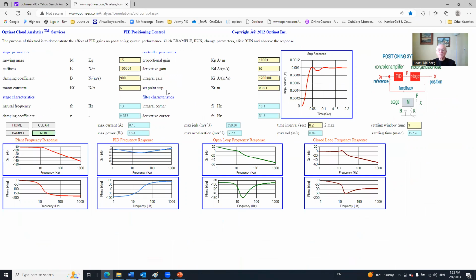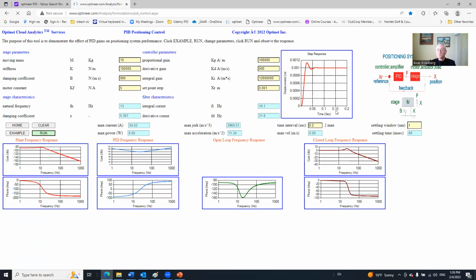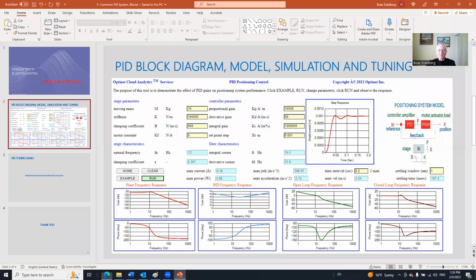We see over here all the variables. We can try to tune it, and this will be part of the exercise that we'll do in homework. But if, for example, we change the control parameters, adding a 0, increasing them by a factor of 10, all of them based on the reference. The objective is to decrease the settling time, and if we run it, then we see that if it was before 150, now we tune it a little bit, it is less than 100 milliseconds settling time.